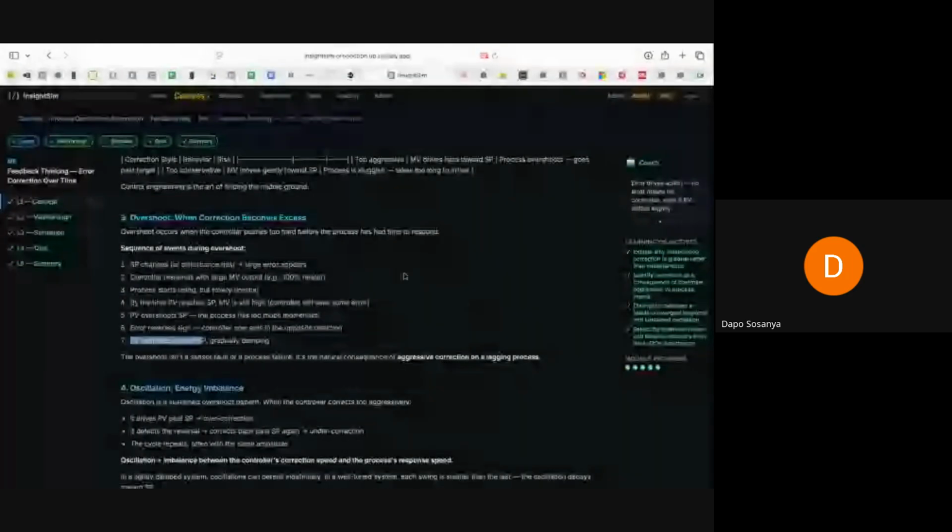So you now realize that the PID adjustments we are doing are, number one, to reduce this up and down oscillation. Number two, even when there is oscillation, we want to reduce the time it takes for the damping to occur. So you can begin to say that PID is not something really complex in that sense.